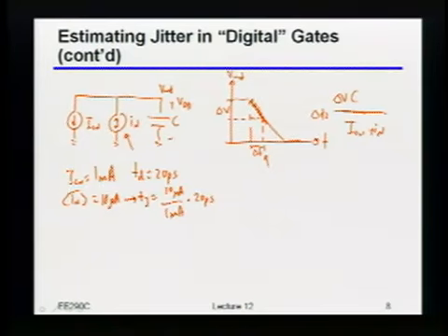Now, again, I didn't do it in variances here because I already did all of that. That's how I came to the 10 microamps in the first place. But the point here is that whatever that variance of the noise current is, if you normalized it to the on current, that's sort of like telling you the signal to noise ratio. And once you know the signal to noise ratio, you can use that to figure out the actual timing jitter, because the signal in time is kind of like your nominal delay.